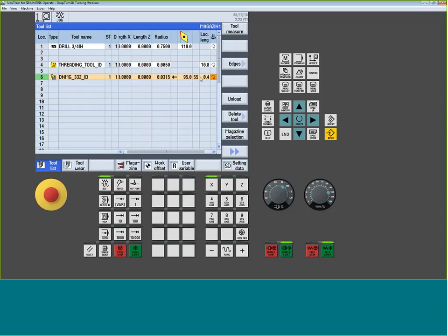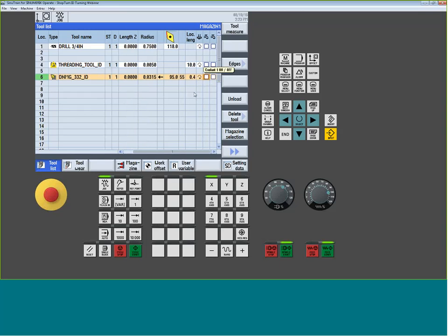This is more of the picture. I mean, yes, I guess in theory you could say that I can see the back side of the insert when boring. The problem is you got a boring bar that's even further out than that. So it's not really helping you too much here. I guess you could put a bigger IC to try to track the back of it, but I wouldn't necessarily go that route. Certainly we're in ShopTurn, so we need to denote the direction that the spindle is going to run in. And if I was flipping something over, doing an inverse, then I can change my direction here and then my flood coolant. So that's pretty standard.